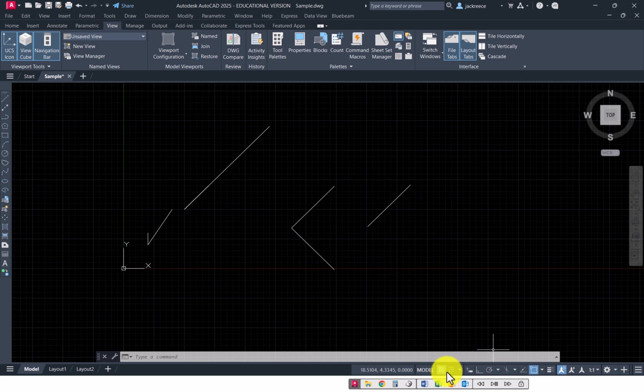One thing to remember: if dynamic input is turned on and you type a comma between the values, that tells it you're doing a relative distance based on those 2 points. But if you use the tab key between the 2 numerals, it's telling AutoCAD that that is an angle. All right, so let's stop this video and then we'll come back with the next one to talk about ortho and polar tracking and some of the settings.